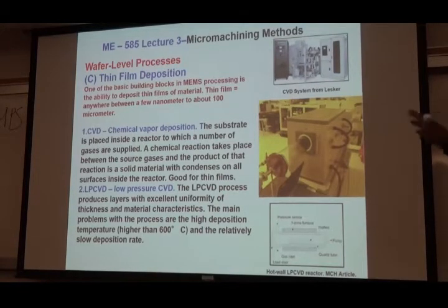Pressure, typically in these processes, either you have atmospheric pressure, okay, 1 atmosphere, because you don't want to pressurize. Pressurizing is expensive. But you could do vacuum. Vacuum is also expensive. But vacuum makes things interesting. So, when I ask you about pressure for a condition, I want you to realize it's either 1 atmosphere, or it's partial vacuum, or it's total vacuum. If it's total vacuum, of course, you can't put stuff. If you're putting stuff, then it has to be partial vacuum. Okay? So think process. I mean, there's some sense to how these things are done.